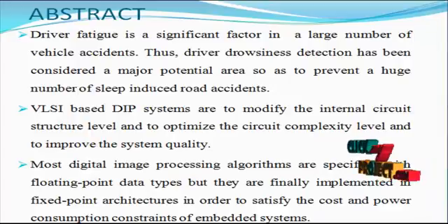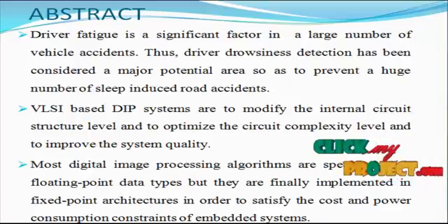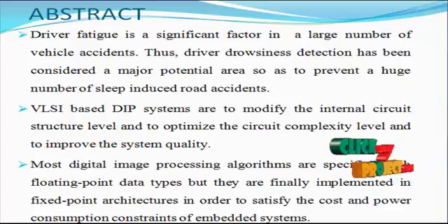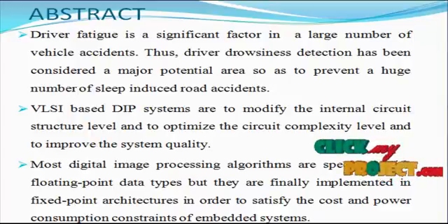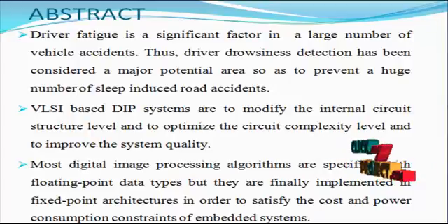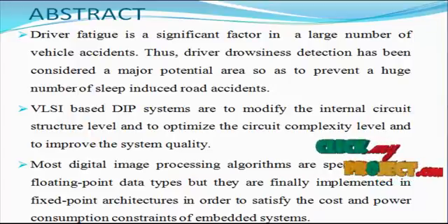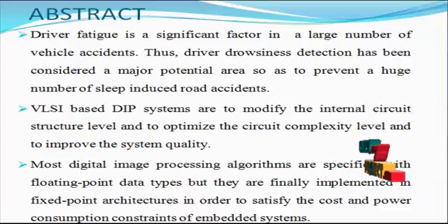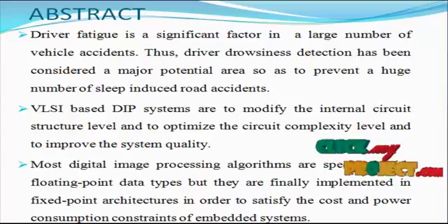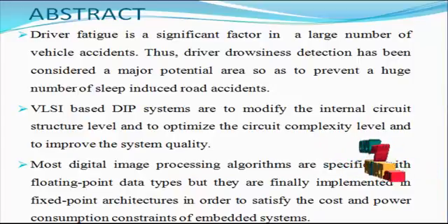The third set of techniques is based on computer vision systems, which can recognize the facial appearance changes occurring during drowsiness. Physiological feature based approaches are intrusive because the measuring equipment must be attached to the driver. Vehicle and visual feature based approaches have recently become preferred because of their non-intrusive nature.